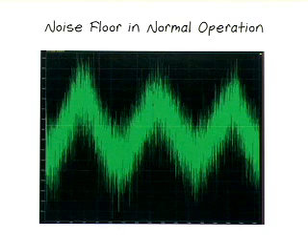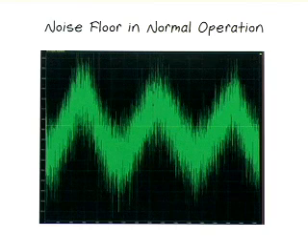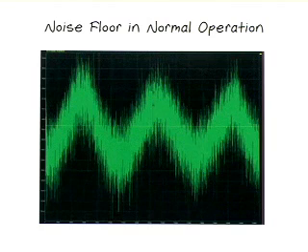In applications where poor layout is used, these peaks can be up to 20 dB. If this were a narrowband application that happened to collide with the elevated regions of the noise floor, this represents a real loss of SNR on the order of 20 dB. While good layout can help reduce the effects of digital feedback, it may not be enough to eliminate the problem. The LTC2261 helps reduce digital feedback by providing a new proprietary mode to help mitigate it, called alternate bit polarity mode. Let's take a look at an example where digital feedback is likely to occur.